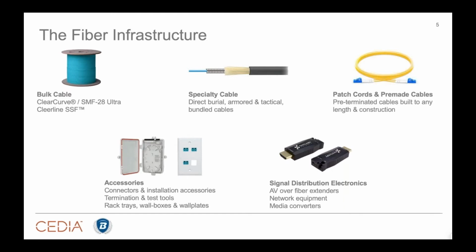Well, in the fiber world, it's incredibly common to buy a pre-terminated cable that really comes in any length, any configuration. And when I say any length, I literally mean, hey, you've got that gate application where you've got a security camera 2,000 feet away, 3,000 feet away, 2 miles away. Fiber is an incredibly strong, surprisingly strong, very small, pliable cable. Okay, the technology's come a long way, and you can buy a pre-terminated cable that's plug and play that you pull over that distance. And a factory, a machine will build that cable, will put the connectors on, will wrap that cable so you have a secure way to pull it up to 100 pounds of pull rating strength. So these things are strong.